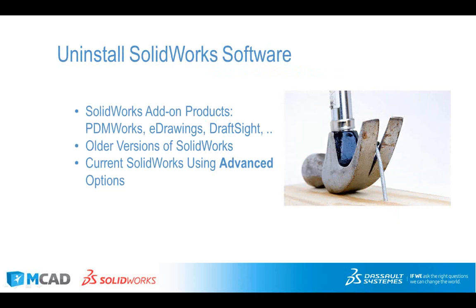So the order here is, if you have third-party add-ins, stuff like that, you would uninstall those first. If you have eDrawings or anything that's listed as a separate item in your installed programs, your add/remove programs, you would get rid of those first. Then you go to older versions of the software.